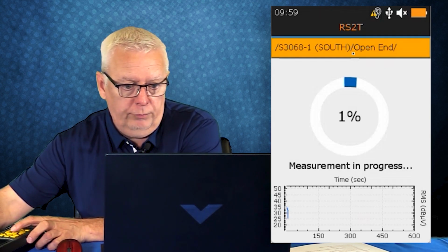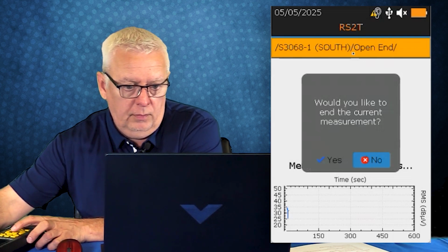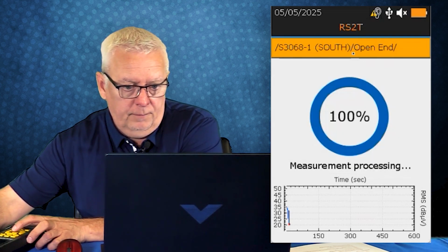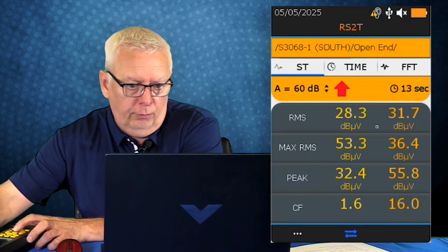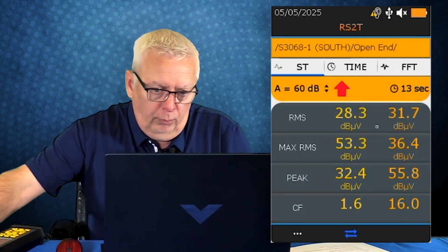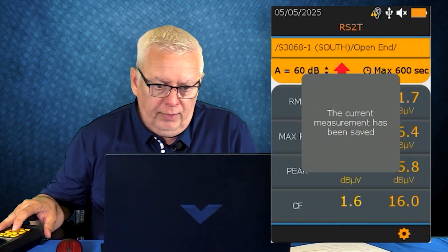And we will record that. Now you're going to see when I hit enter on the screen, it's going to pop up and say my absolute alarm was triggered on a danger because it was above my danger set point of 24 dB, and it actually gives me the information about what my warning and alert values were as well. I hit OK, and then the current measurement has been saved.